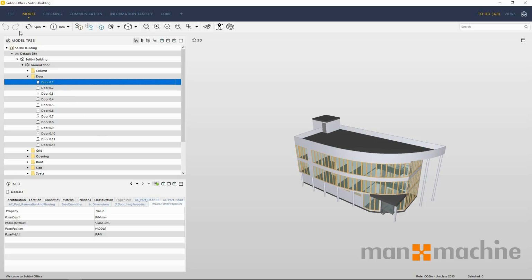At the top of the window we have a menu bar available to us. The first option gives us our navigational tools. We have pan, spin, walk and game navigation. Each has a shortcut assigned to it. Using the keypad on my keyboard, pressing 1, 2, 3 or 4 will go into the relevant mode.